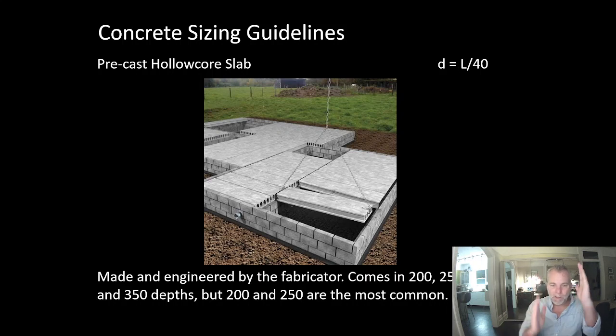From a shear transfer point of view, you need concrete in the middle, but its utilization is very low, so you don't need all of it. You need maybe a quarter of the concrete to transfer the shear. Hollow core precast is an ingenious response to that. It takes all of the concrete out of the middle, which makes it substantially lighter. It's manufactured off site, so erection is quick. So hollow core is an ingenious product.